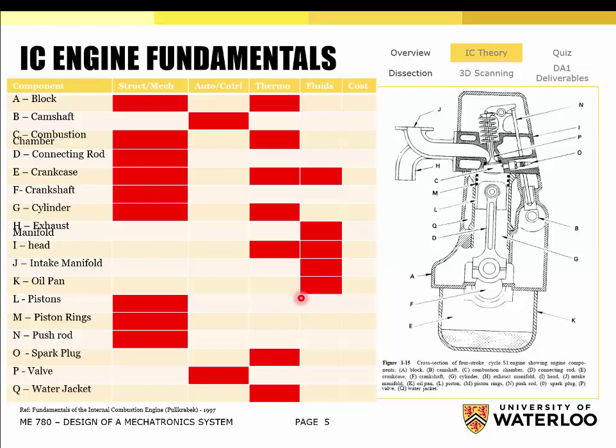But if any of you have been go-karting, what happens when you put that engine in a go-kart and you go around a turn? What's going to happen to the oil in the sump? Raise your hand and give me an idea. What? Yes, over there. Exactly. So the centrifugal force of the turning force from being in the vehicle will actually force all of the oil to slosh to one side.